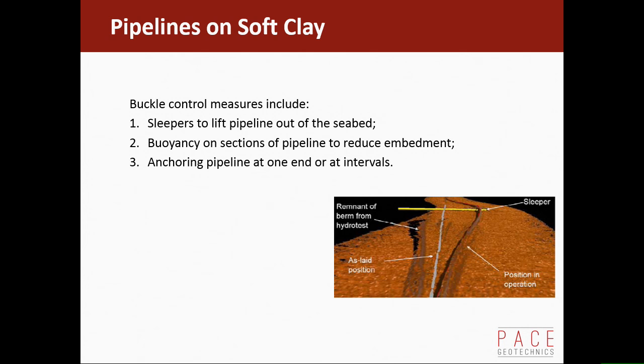By snake laying like that and putting a sleeper at those 2 points, when the pipeline expands, it expands that way and that way and that way and that way. So it's expanding into the buckles so that it will try and adopt that shape.